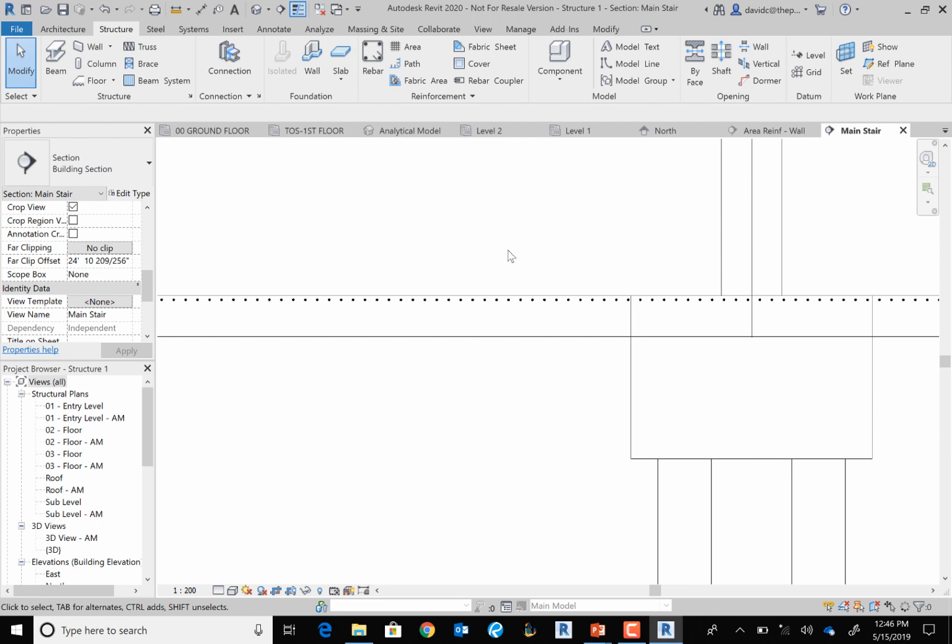The only bad thing about it is they don't come in parametric at all most of the time when you're doing that. But with Revit, you have the Pick Lines tool. A lot of times, if you do have line work that's coming in, or it does bring in a 3D model, if you can get into those individual views and utilize pick lines, a lot of the time that's going to speed up your modeling process, I would think.